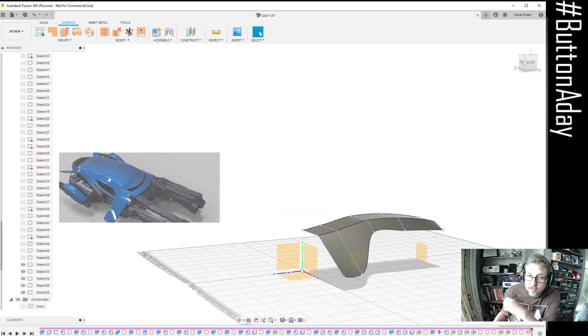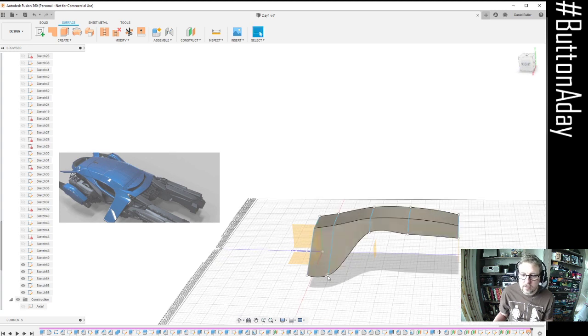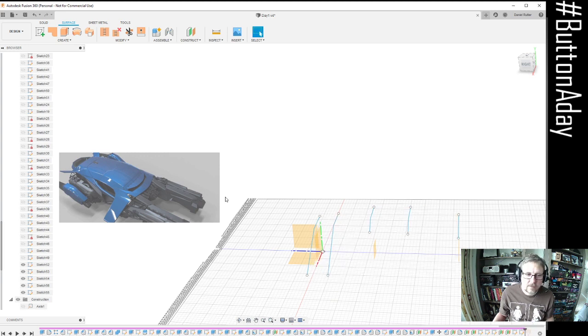And now the other thing we're going to try and do is a 3D sketch again, which I have fallen into difficulties with in the past, but we'll give it a go. I'm going to try and define this line that makes up the edge around here. And I'm going to try and hit all of these points on our ribs that we've made, and then I'm going to specify that as a guide rail so that we have some real control over how this edge of our surface is going to flow.